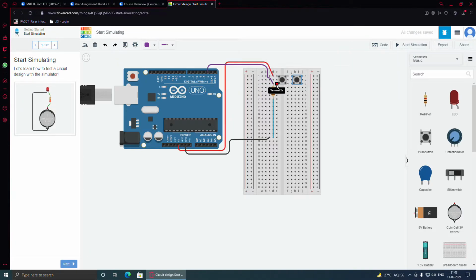Now we have to use the other terminals for the other function, which is the triggering of the switch. So we are connecting terminal 2A to pin 2 of the Arduino. We might have connected this to pin 4 or, say, pin 6, but in the program we are using pin 2. We could have used any other pin, but we are using pin 2 as the trigger for the input.